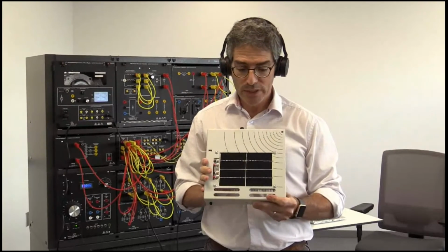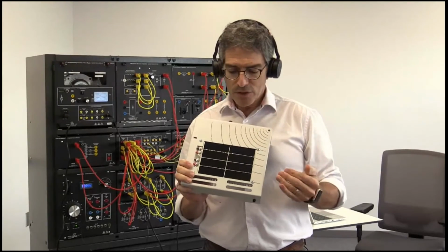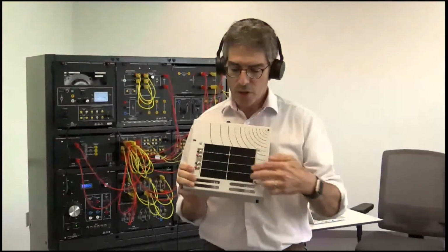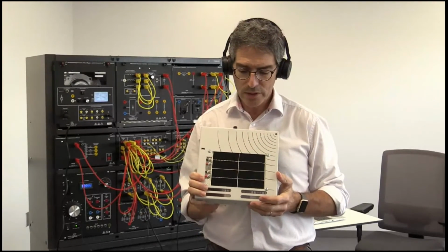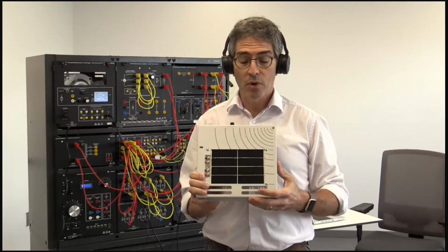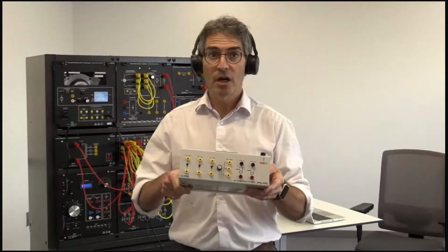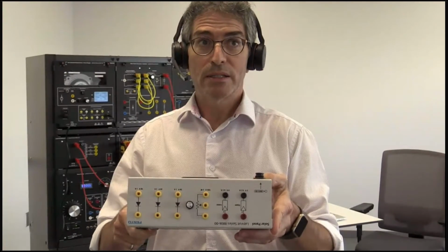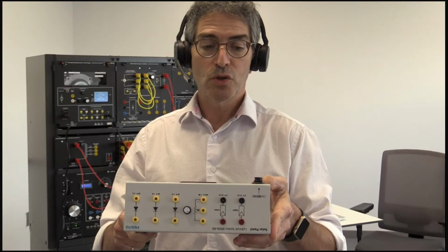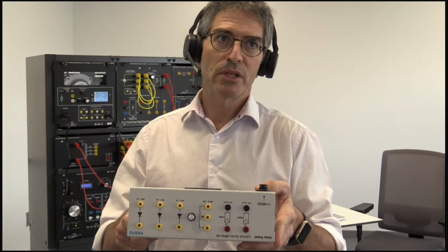So you will get 2 watts of electricity out of it, but it is a completely functional photovoltaic panel with 2 separate modules that you can connect in parallel or in series, depending on if you want more current or more voltage. Then it also comes with diodes on the top here that will allow you to do some experiments with these to bypass certain modules when they are in the shade, for example, or prevent the battery from discharging through the panel during the night.